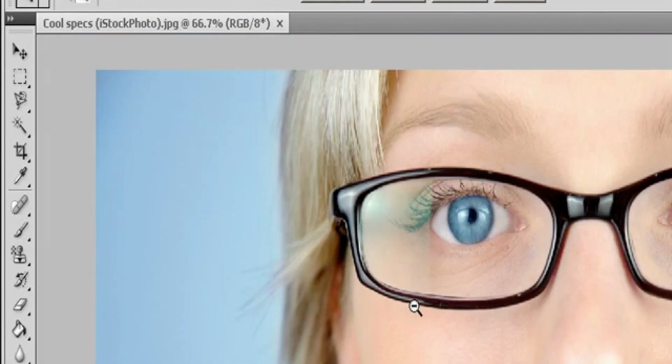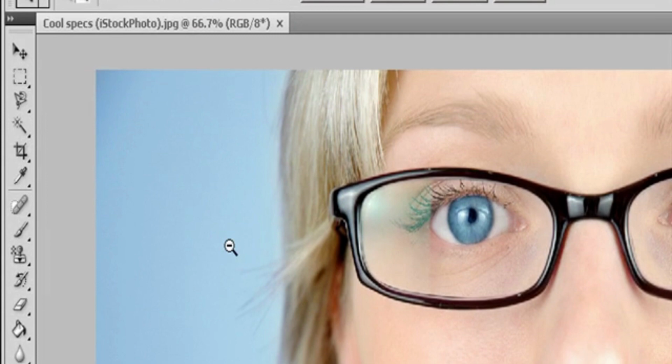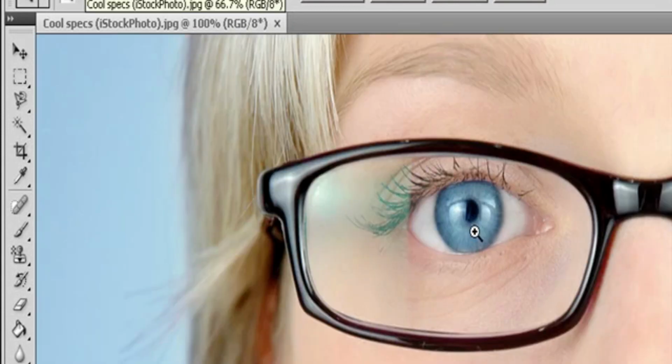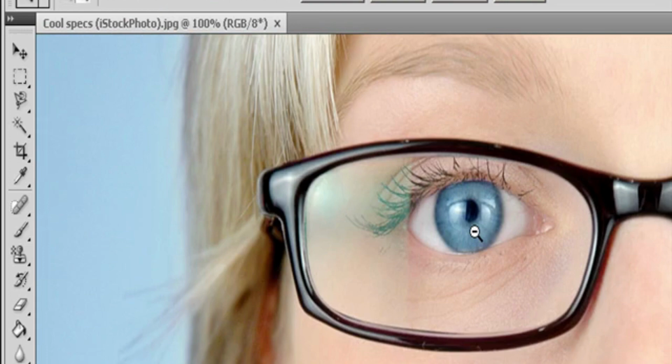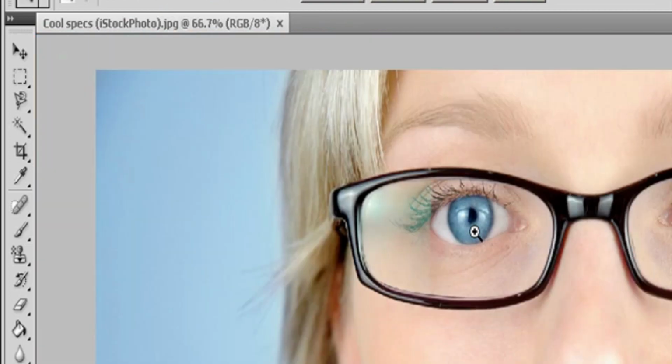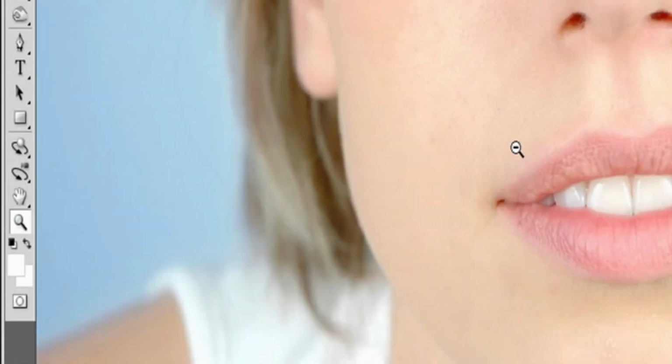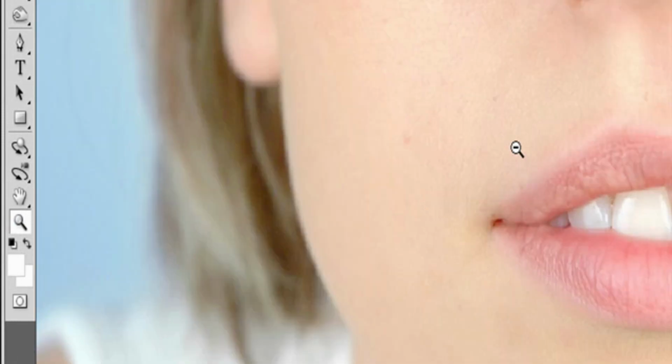Select the Zoom tool. The pointer becomes a magnifying glass with a plus sign in its center. Click the center of the area that you want to magnify. Hold down Alt in Windows or Option in macOS and click the center of the area that you want to reduce. Select the Zoom tool and then click-hold in the image for a continuous motion smooth zoom in. Alt-click-hold in Windows or Option-click-hold in macOS to continuously zoom out.